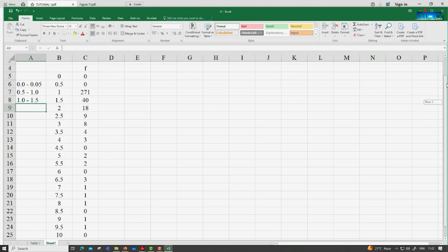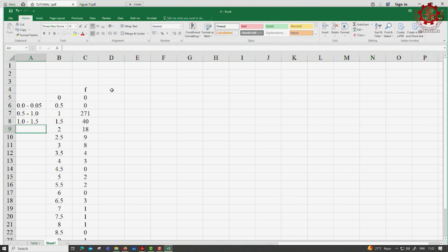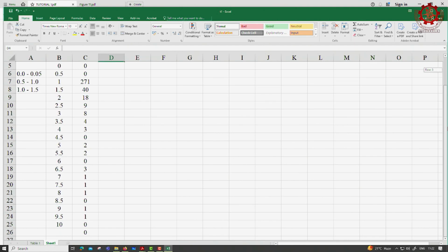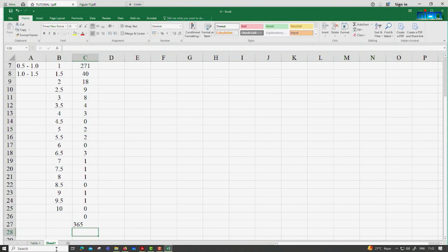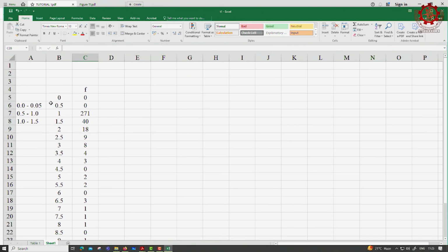So, now we can convert this to a flow duration curve by the technique I told you earlier, right. So, you can get the probability. Altogether there are 365 data points. So, we can count it, the total is 365 data points. So, the probability of each day's flow is really the frequency divided by 365.